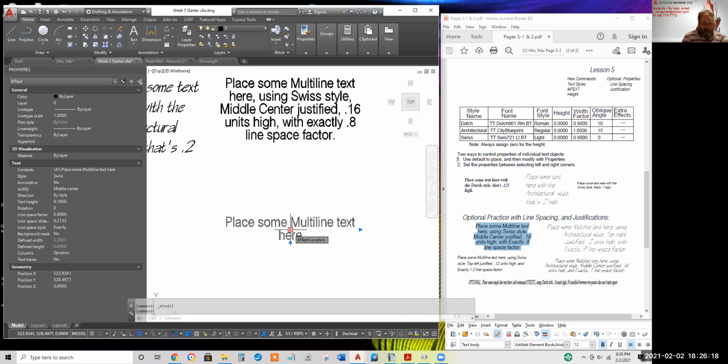So I like to use middle center again when labeling a room. If I copied the men's room and put it across the hall for the women's room, the word women will be perfectly centered as was the word men without having to move and recenter the text, provided it started with this middle center justification. So far, so good.